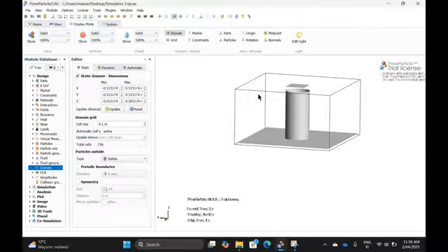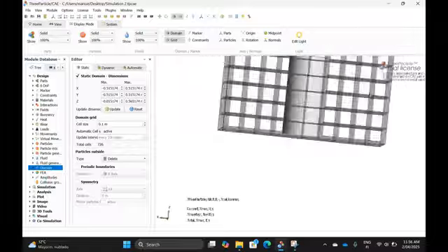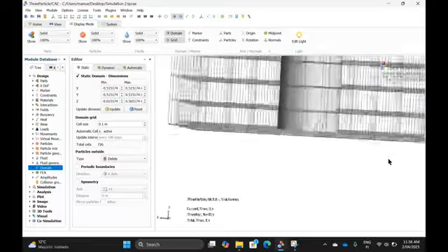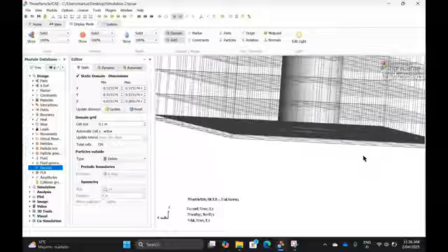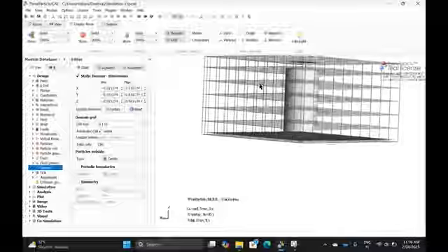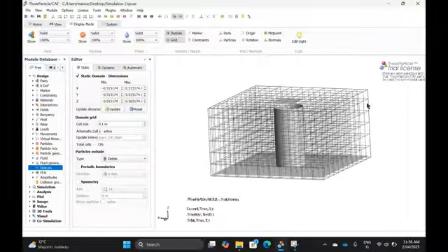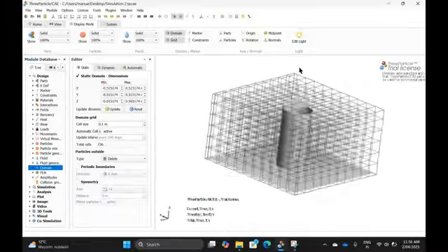What is the cell size? Here you can see that this is the cell size. I also do not want to exaggerate that, because this is a science for itself, the appropriate setting of the cell size. A good rule of thumb is to set the cell size in the area of the size of your smaller particles.